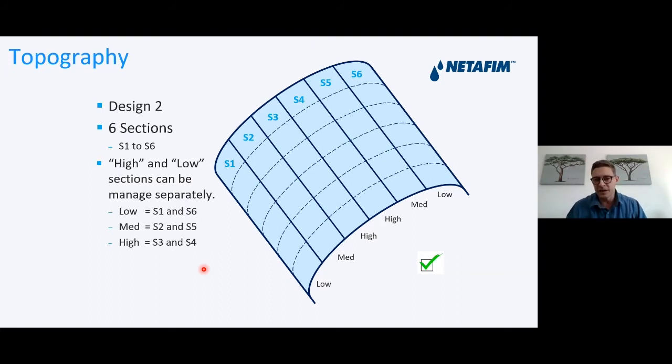In actual fact, if we look at it practically, we normally see that in the lower lying areas, we irrigate a couple of hours less than we irrigate the higher lying areas, because we know that the lower lying areas tend to run a bit wetter. But now again, with the dedicated main lines and the designs that we do according to soil type and according to topography, we can now very accurately and very efficiently treat the different areas as they are supposed to be treated, and we monitor it as well.